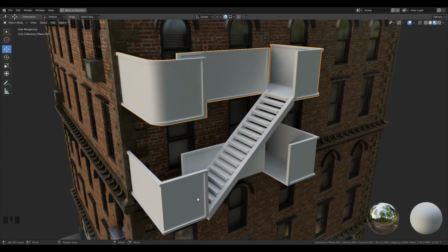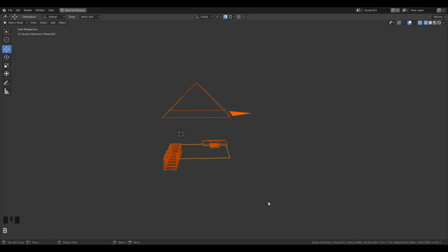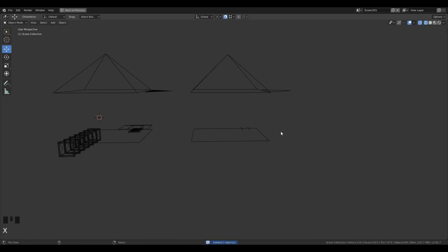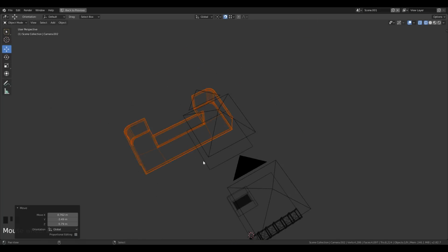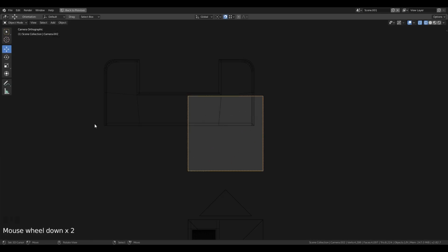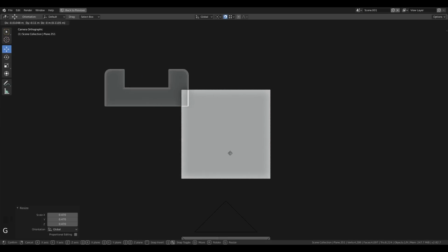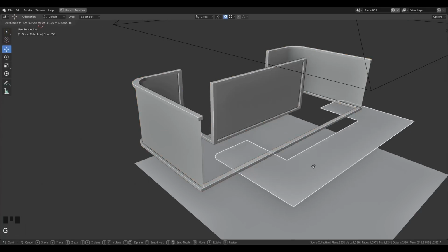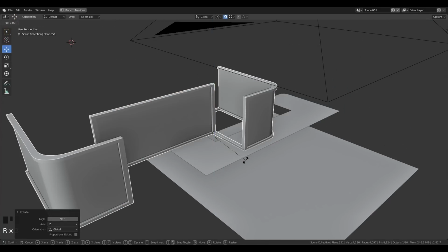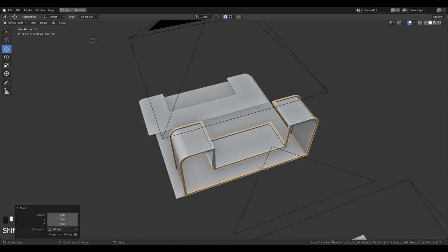Now just like before, copy and paste the mesh in the second scene. You can also duplicate the whole setup for baking again. It will help you to work on different textures individually. You will need to separate the floor from the stairways so that you can work on it separately and move the other mesh outside of the camera view. Just position it in such a way so that you can use it as a reference for the height of the grill.